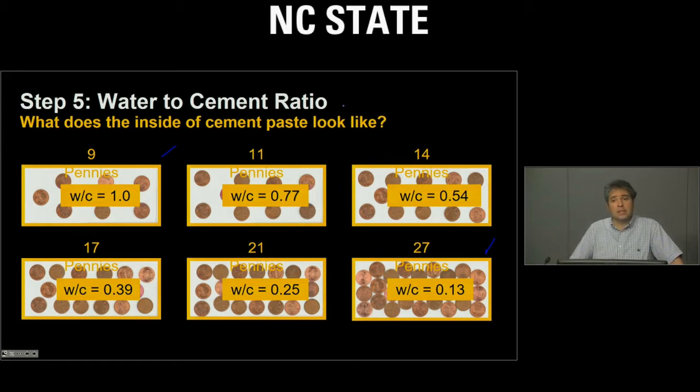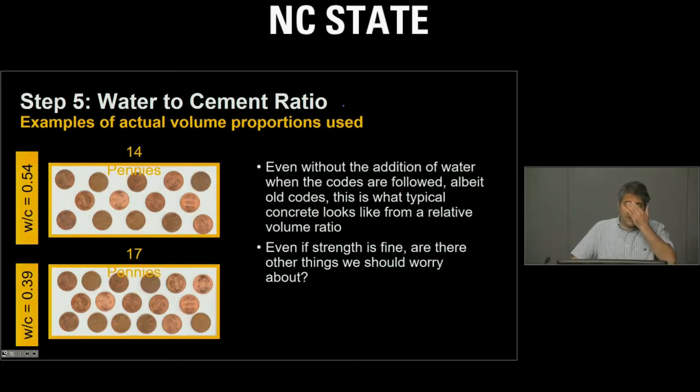The lower porosity you have inside the system, the lower permeability you have, less water moves through the system, and higher durability therefore. And of course, the lower porosity that we have inside the system, the strength of the system increases quite a bit. So now, if you look at the concrete, the normal concrete that is generally being used in